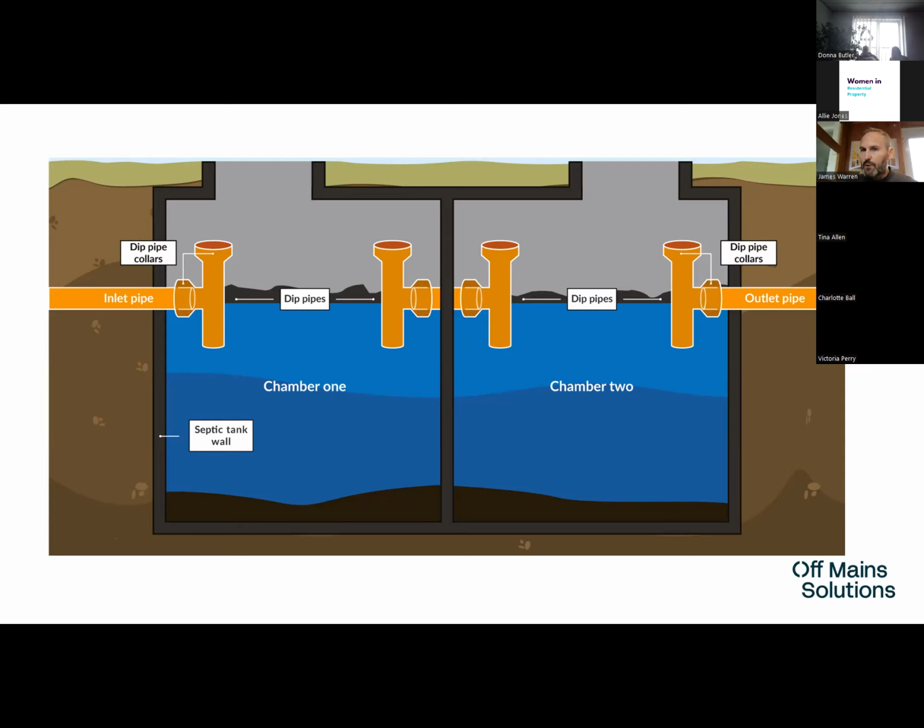And that's really critical, because if you get solids or fat, oil and grease that escape a septic tank, if it's going to a soakaway, it will quickly cause it to fail because they're not designed to handle that matter. But if a septic tank is incorrectly discharged into a watercourse, then all the wrong matter that should be inside the tank, if it's allowed to exit, causes pollution inside that ditch, that stream, that river, whatever it may be. So the way it's controlled is, A, don't let any rainwater come into these systems.